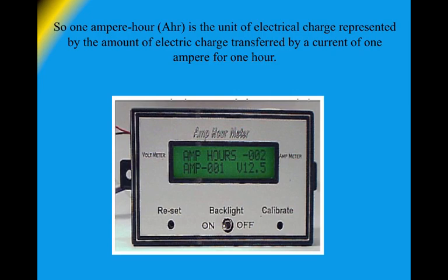Cumulative amp hour meters come in many varieties, but the best ones not only use shunts to measure the current flow into and out of the battery, calculating the amp hours, but they also calculate the aging of the battery and adjust the Peukert's constant, which we will learn about, to adapt and understand the actual capacity remaining in a battery as the battery ages.